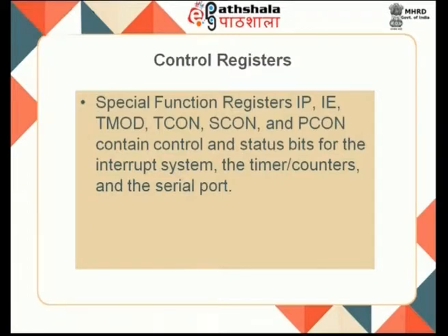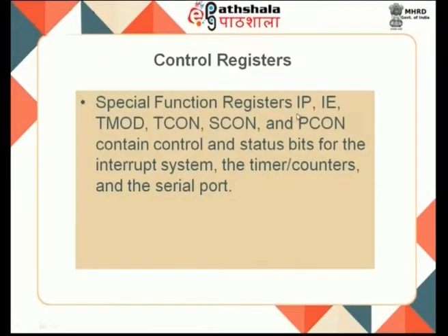So, when you are looking at special function registers, I can call these control registers, where we will be having IP, IE, TMOD, TCON, SCON and PCON. The interrupt enable is used for interrupt handling, and TMOD is for timer control.